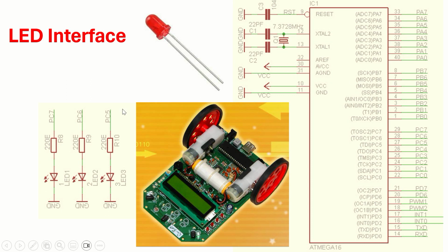So calculate, use Ohm's law. If you have applied a voltage of 5 volts, we are assuming that our entire board is operating through USB. So the USB of computers or any generic supply will give you 5 volts and a maximum current of 500 milliamperes. We expect even our CPU, the black 40 pin IC, and the LCD, every single component, to work on 5 volts. If you apply more than 5 volts, they are going to be damaged, including your motors.